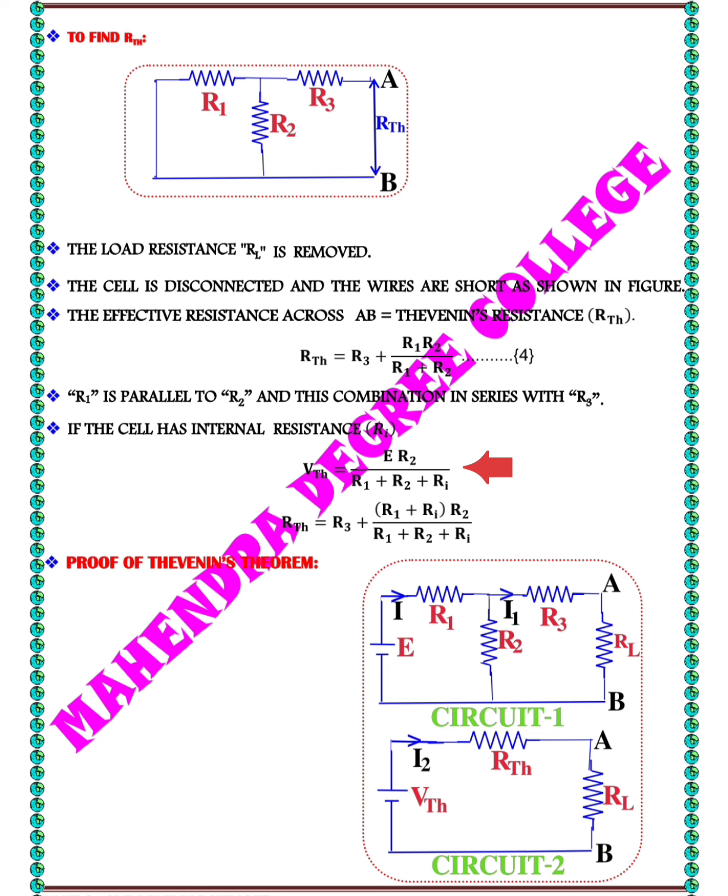Ri and R1 are other resistances in the circuit. The formula represents the output voltage across R2, which is derived from applying the voltage divider rule to three resistors in series, Ri, R1 and R2. It tells you how much of the source voltage E appears across R2 considering all series resistance.